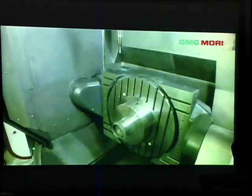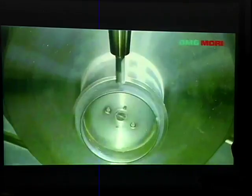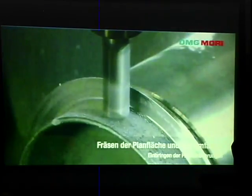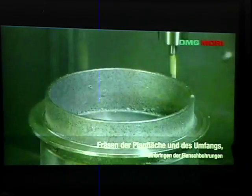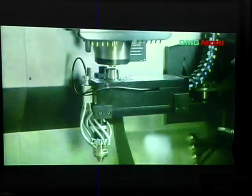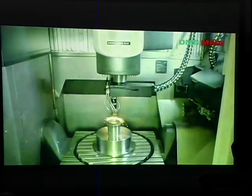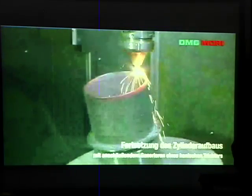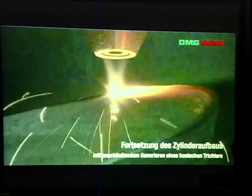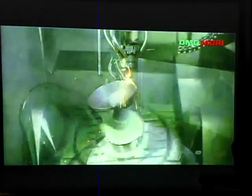We use these technologies as kind of cohabitive technologies to get the best results of each one. You can smooth things out, and then once you're done, you can switch back to the 3D print head after you drill these holes. If we made that hole wider, moving outwards like a cone shape, you can't get to where those holes are cut. So I 3D print a rough shape, I modify it with the cutting head, then I 3D print more, and I 3D print this bevel or cone shape that prevents me from accessing those holes directly, and I just keep switching back and forth until I get a complete shape.